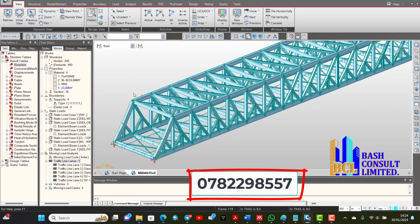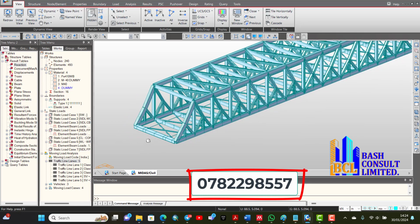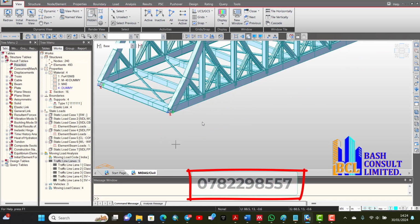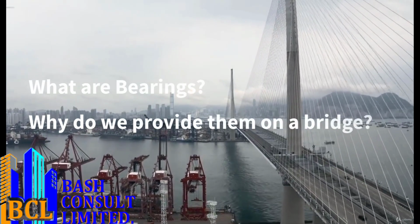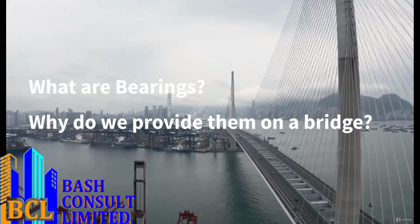So from this software, we can display all the properties about the bridge, right? Like we have the boundary conditions that we provide. Among the boundary conditions are the provisions for bearings. These are the points where we have the supports. The bearings can be in the form of elastic links or rigid links. They are mechanical components that are provided to the bridge between the substructure or abutment and the superstructure.